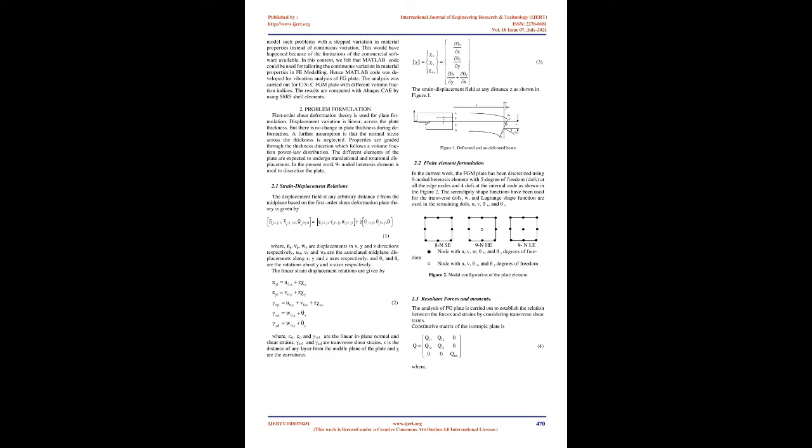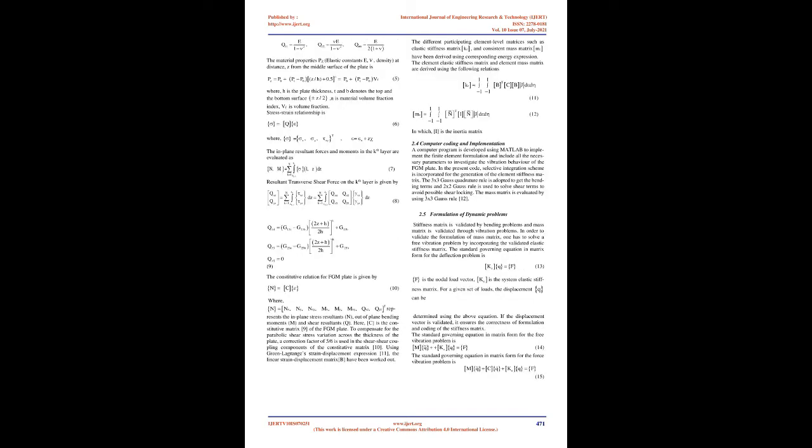J. N. Reddy [7] has studied theoretical formulation and FEM model based on TSDT for FGM plate. The formulation accounted for thermomechanical effects combining change with time and geometric nonlinearity. In this higher order theory, transverse shear stress was expressed as a quadratic function along the depth. Hence this theory requires no shear correction factor.